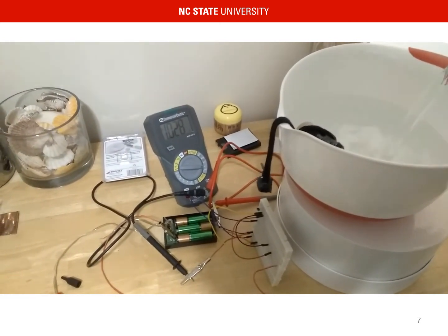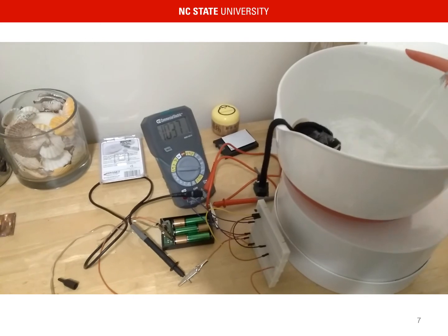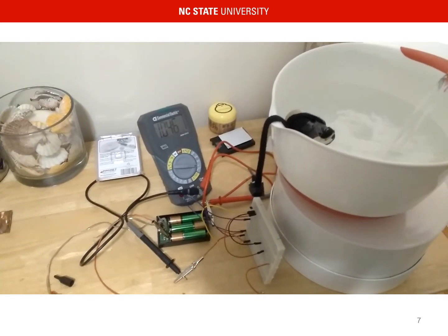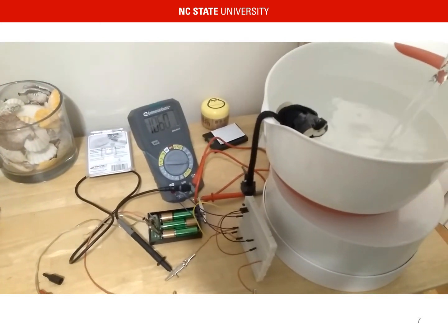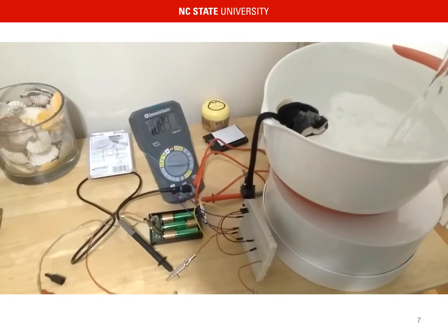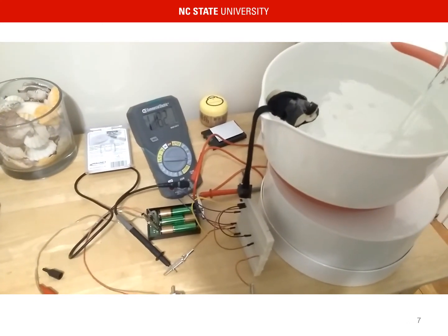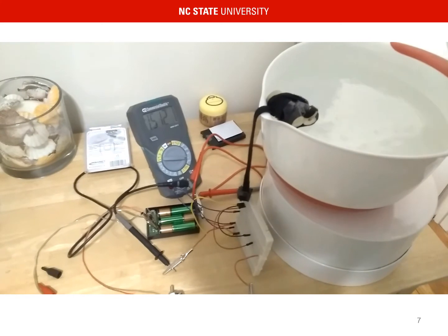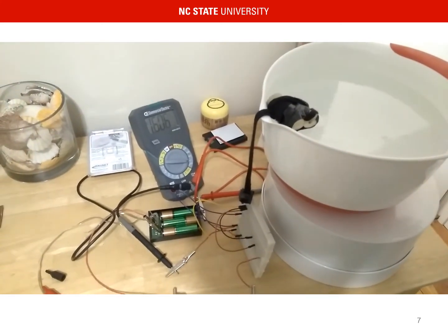As water is added, the magnet begins to descend towards the sensor. Magnetic flux density increases exponentially as distance from the magnet decreases. This explains why we see the voltage increase at an exponential rate as the distance between the magnet and the sensor decreases linearly. Our final reading is around 1.78 volts.